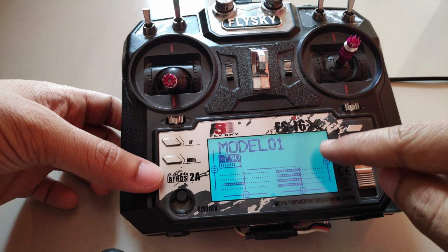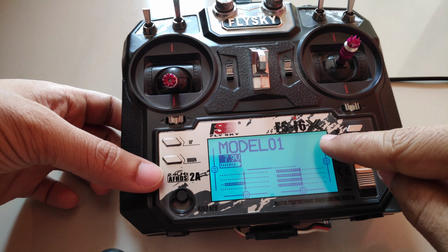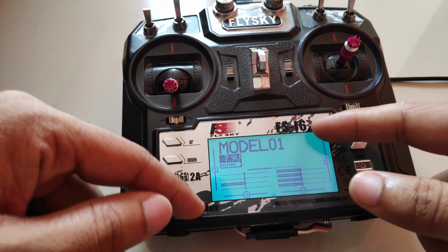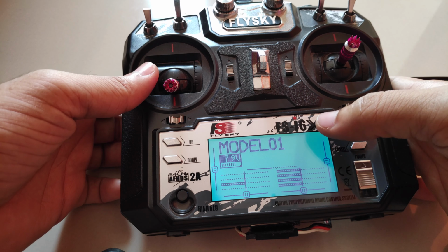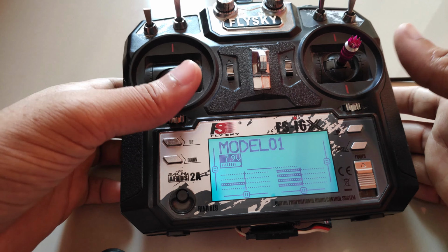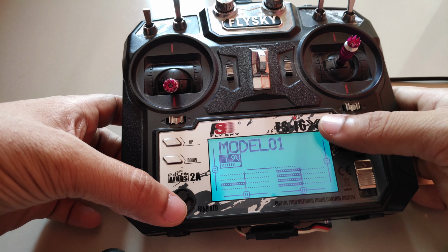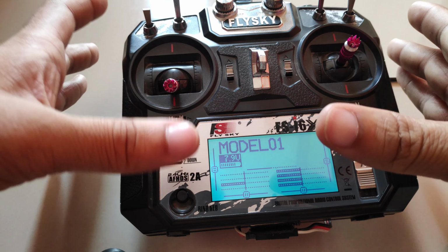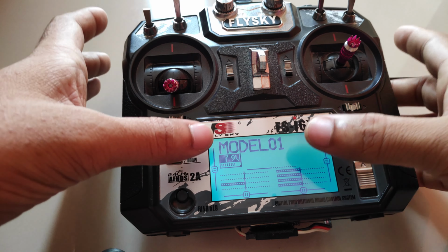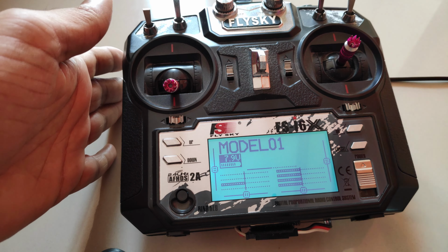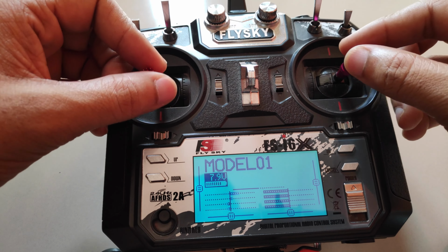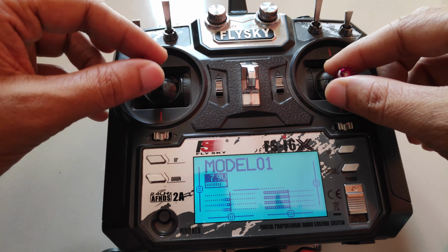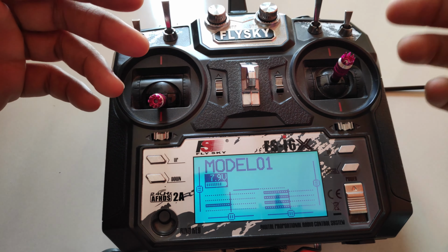And I've disabled the USB joystick mode and the square icon is off. And as you saw, I did not have to restart the radio from a USB reboot issue, because then there would be an exclamation mark over here, and that would indicate that the radio would have to be restarted. And since we did not have that, it clearly indicates that the USB joystick feature is improved and a lot better. And also when you're using the radio with a simulator, you will notice that the latency is also reduced. So the simulator experience with this radio is now improved and enhanced.